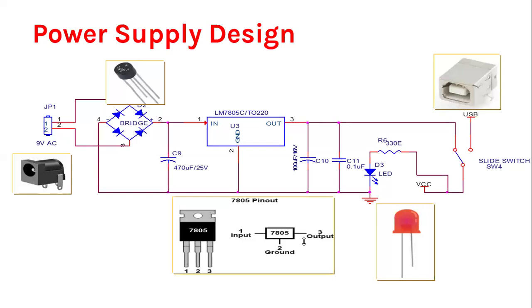So V equal to 3.5 volts, I equal to 50 milliamps. Is 50 milliamps of current required to glow the LED? No, only 10 to 20 milliamps of current is sufficient. For safe operation, 10 milliamps is sufficient. For example, if you are using a red color LED, it requires only 2 volts and 10 milliamperes of current. Now find out the resistance value.